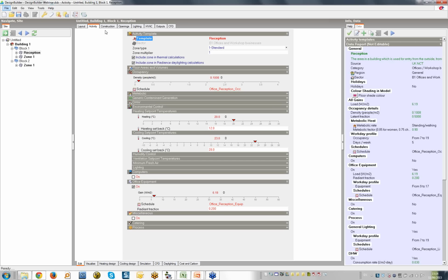Energy modelers and designers generally recognise the importance of moisture when considering internal conditions for spaces such as museums, requiring close humidity control. Moisture can also have a significant effect on internal comfort conditions and the performance of air conditioning systems. To accurately assess cooling system performance during periods when cooling is needed, you may need to know the moisture conditions of the building. Using the more advanced moisture models can be one way of closing the gap between predicted and actual cooling energy consumption.